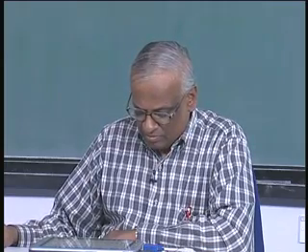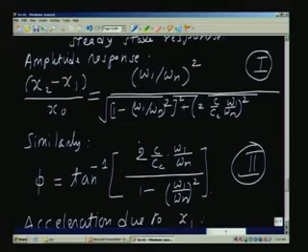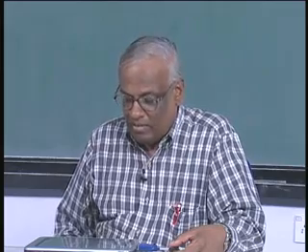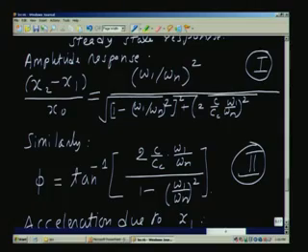If we go back to the slide, the equations which we had derived in the last lecture were labeled as 1 and 2 here. The amplitude response of a second order system, which consists of a mass with a spring, where the movement is against the spring, and there is a damping. The damping can be due to viscous effect, and the response is written in terms of the response to a sinusoidal input. That means that the vibration imposed on the system has a frequency of omega 1, and the natural frequency of the system is omega n. So, what we are talking about is the response of the system to the input.